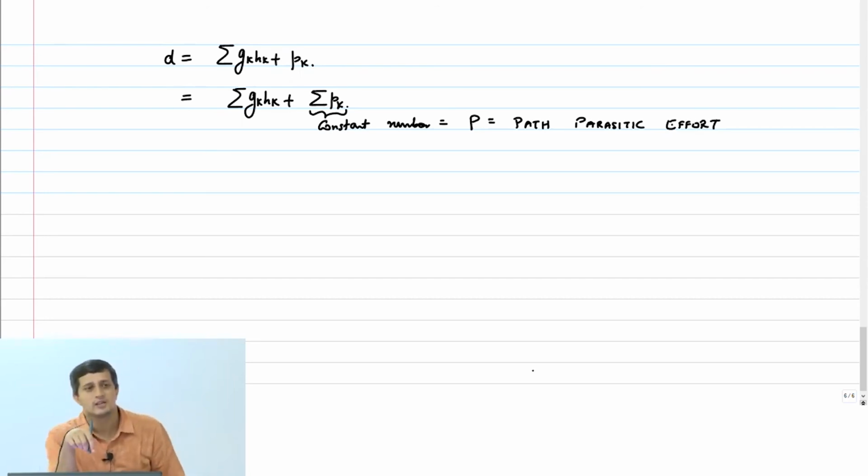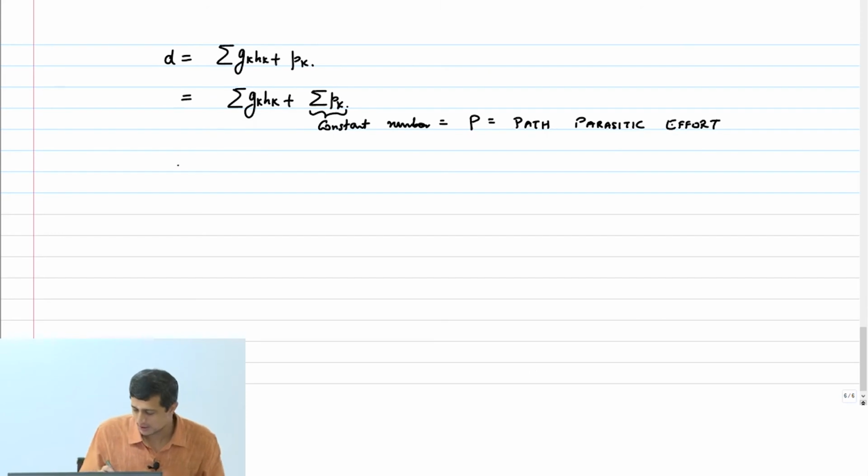Okay, so here is where I told you that it doesn't matter whether you do 7 RC or 6 RC or whatever it is for the NAND gate, contamination or propagation or whatever. It's a constant number that is not affected by my gate sizing problem. So when I do my minimization, that constant anyway goes out. You want to be more accurate, please be more accurate. It does not affect your gate sizing algorithm is all I was trying to tell you there. And therefore it's okay to make the approximation of only counting diffusion capacitances. Okay, so that's a constant number.